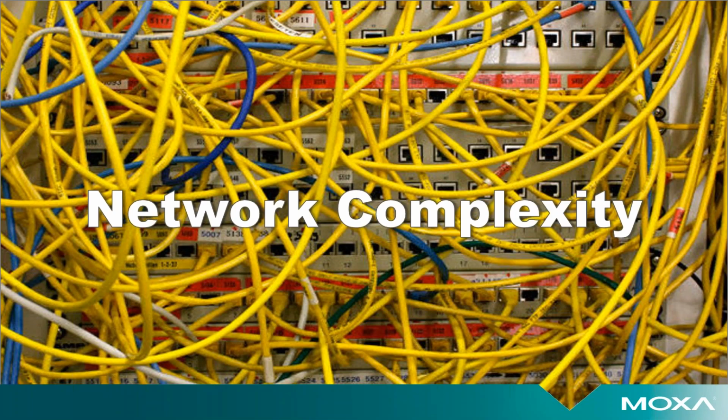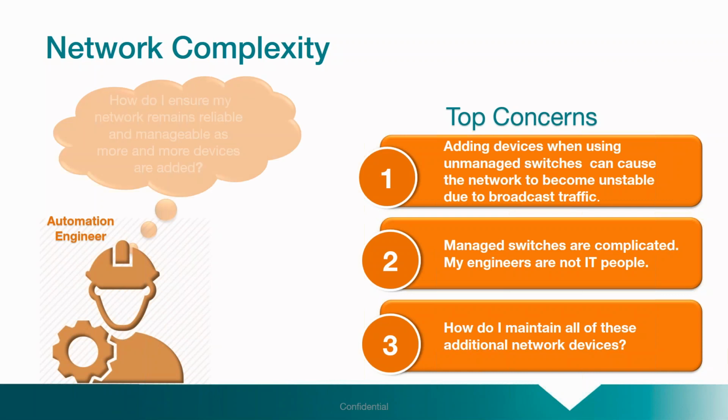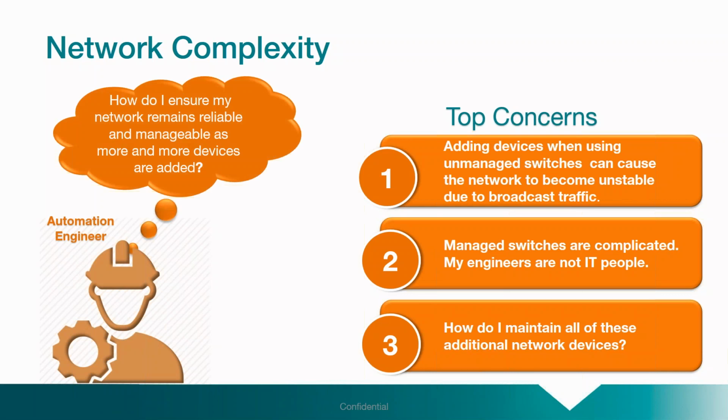All right, next up, network complexity. Like we mentioned before, you want to be able to manage the network as it grows. But the more devices you add, sometimes people opt for using an unmanaged switch because obviously they're operations technology engineers, right? They're not IT folk. So if you are connecting these devices to unmanaged switches and you're using industrial protocols like Ethernet IP, you're going to be having some problems, and it's important to understand exactly why. So we're going to cover a little bit of that as well.